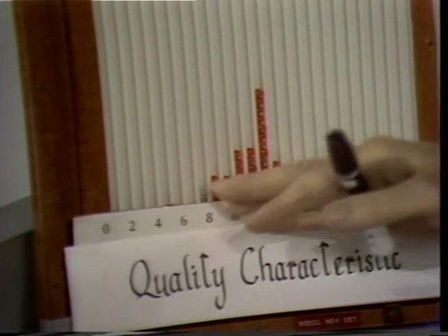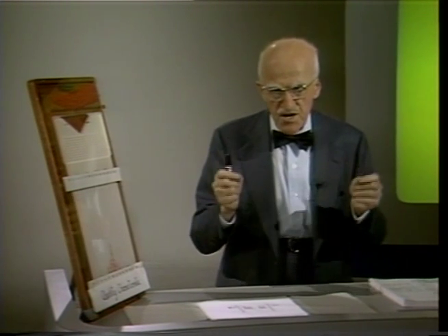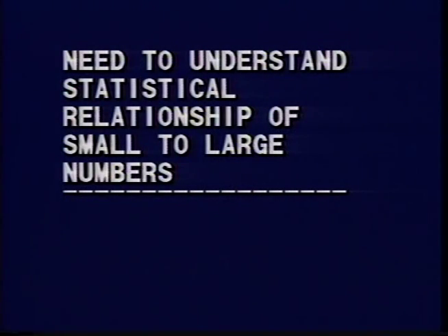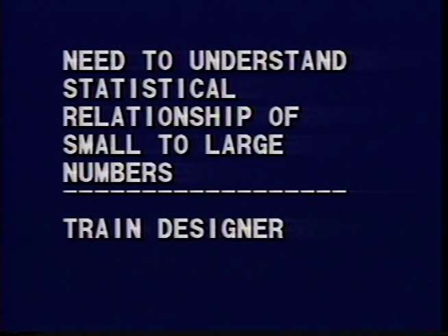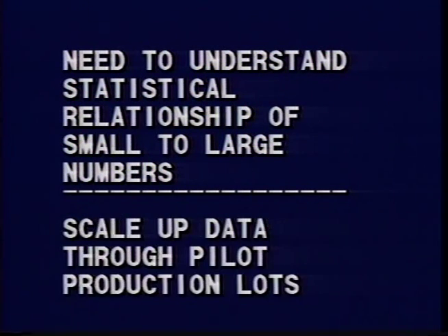Notice the wider range of dispersion. Many units are out of tolerance. The need here is to establish the correct statistical relationship between small and large numbers. The alternatives include train the designer in statistical methodology, or bring in a specialist in statistical methodology to work with a designer, or scale up the data through pilot production lots.